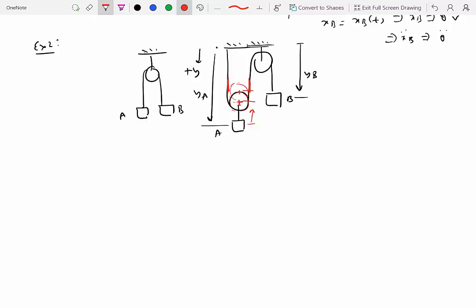And of course, you assume that there is no slack in the system. So this 1 inch and 1 inch together, which will be 2 inches, will wrap around this pulley right over here, and it will be released on the other side. Which means that B would actually come down by 2 inches. So if A went up by 1 inch, B would come down by 2 inches. In this case, you could have seen what was going on just by examination, right?